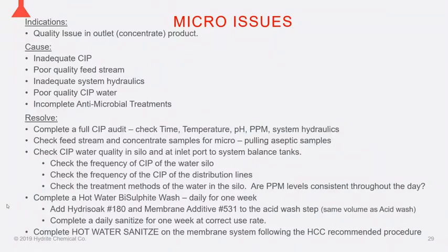And the other thing to add is this can come up a lot of times if there are membranes that are just sitting in water, if they've got a lot of downtime and they're not using a soak. Our soak products like the Hydrosoak 180, that's really where they shine. They're going to be in those systems when they're down, and they're going to inhibit growth. They're not in themselves going to be as aggressive as a sanitize, but that's kind of the point as far as membrane preservation. They are going to keep it bacteriostatic.